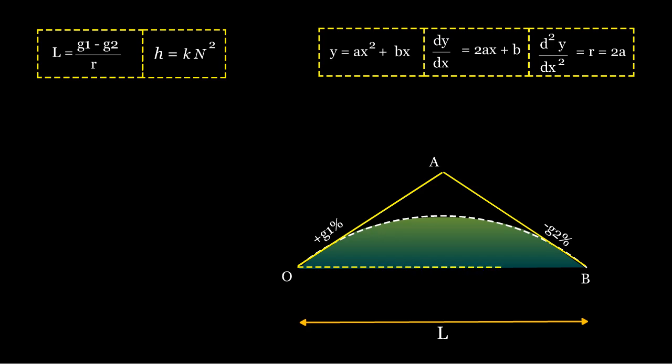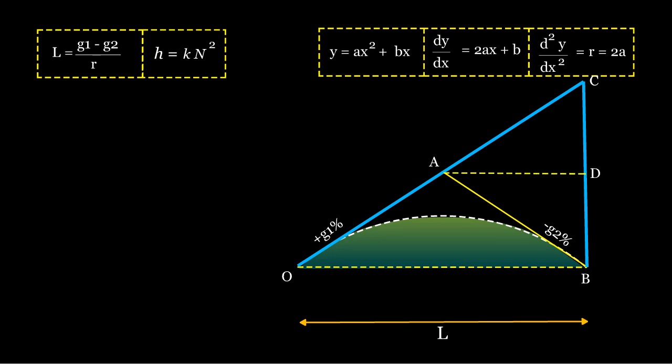Deriving the formula for k. To find k, we extend the tangent g1 to point C, directly above B, then draw a horizontal line CD and a vertical midpoint line FEG. The length of the chord at uniform intervals is L. The number of chords at each side of the grade is n.